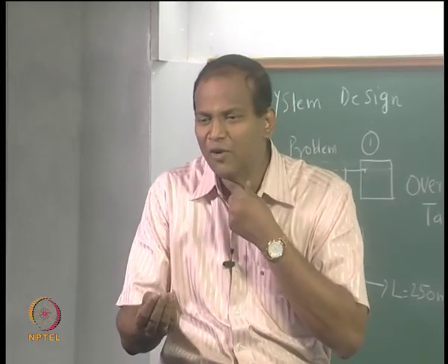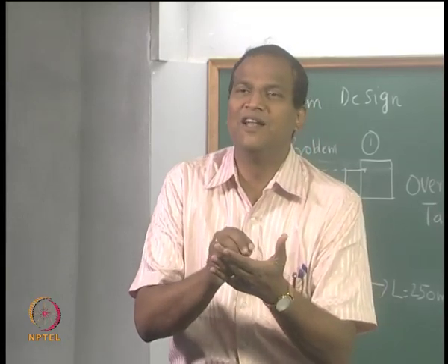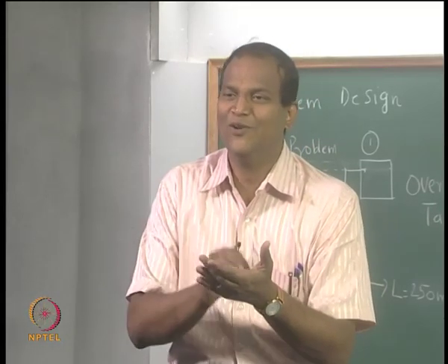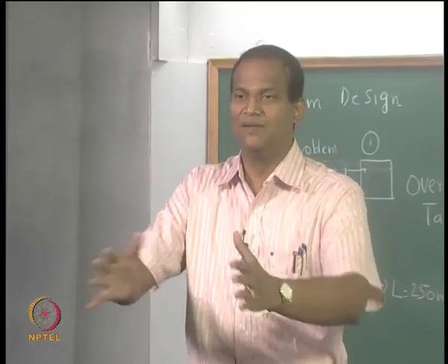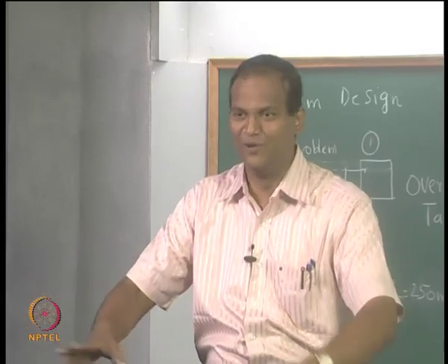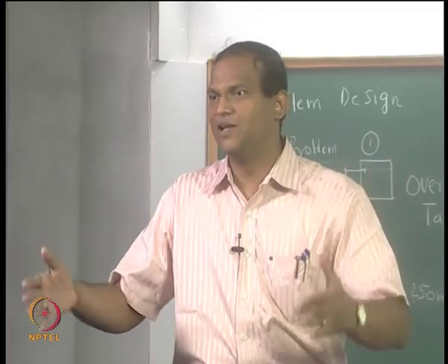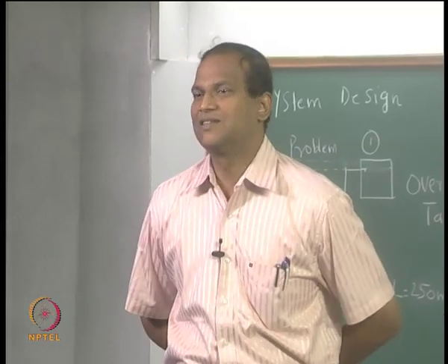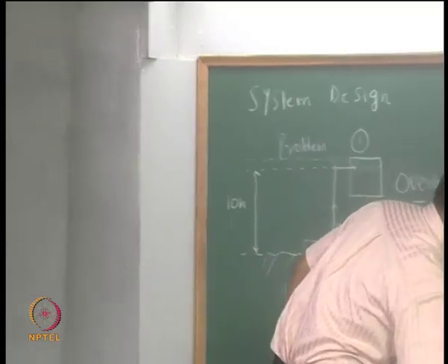So what innocuously started was very harmless, m cp delta T hot equal to m cp delta T cold, Q is equal to U A LMTD. Now you are stuck with so many things. Now there will be an engineering manager, there will be engineers, and then they will do analysis, then they work out cost. So the design is going to be an extremely cumbersome affair because of the various constraints which are built in. Okay. So the design problem is